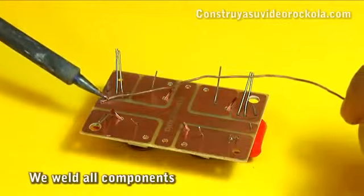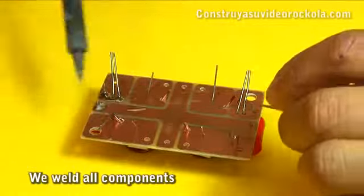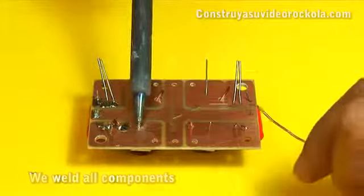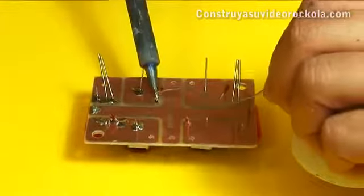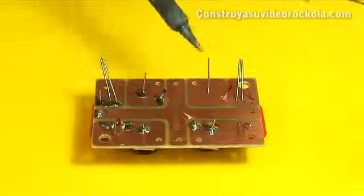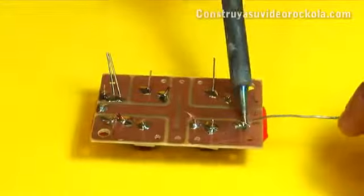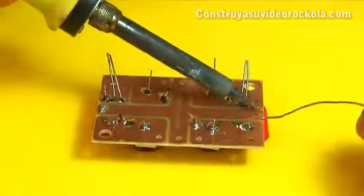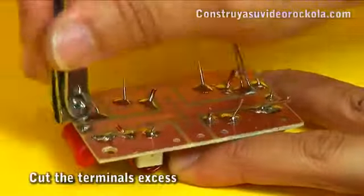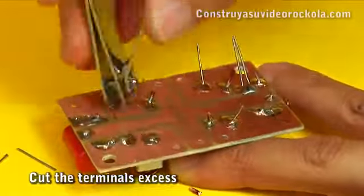We proceed to solder all the components. Remember that the correct way to solder is done by joining the solder, soldering iron and parts to be soldered at the same time. With the aid of a nail clipper or a wire cutter, we cut off the surplus of the component terminals.